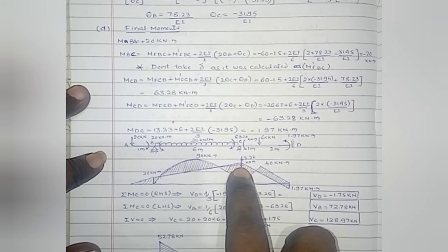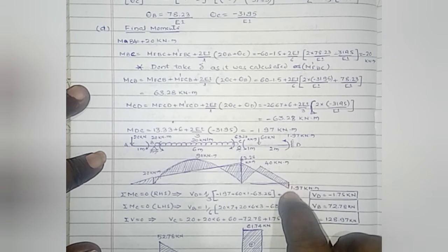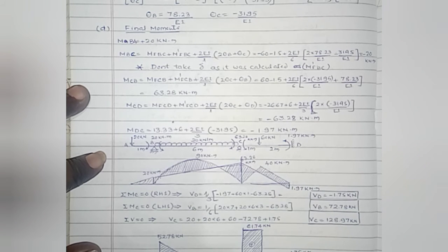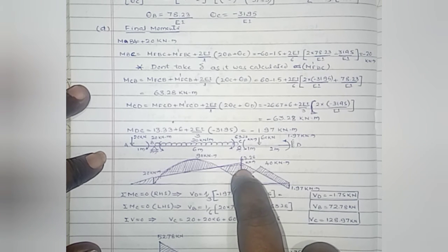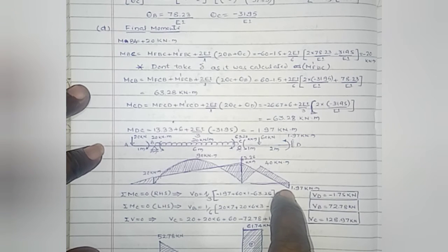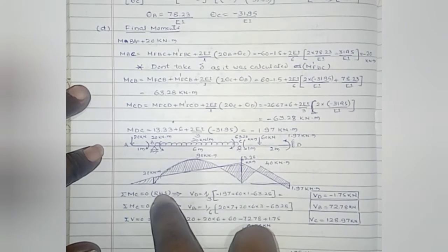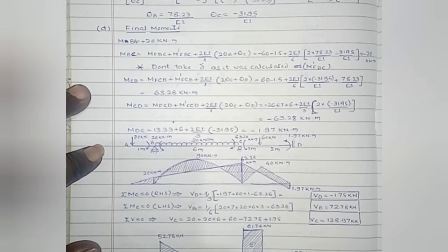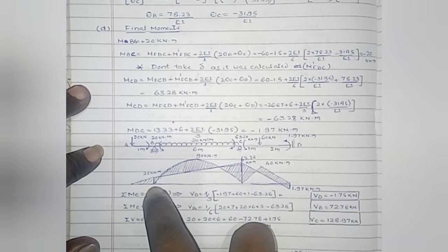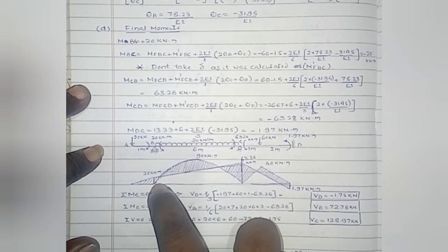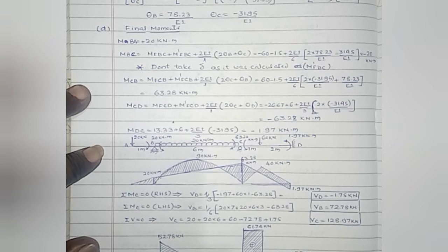Then here at D, the moment is sagging. Hence, we have shown below the reference line, join these two ordinates by a straight line. This one is negative bending moment, this one is positive bending moment. And then the simply supported beam bending moment. Here in between B and C, it is subjected to UDL of 20 kilonewton per meter. The maximum bending moment is WL square by 8 at the center, and at the support the bending moment is 0. By overlapping this, you will get the net bending moment as shown in figure by the shaded portion.